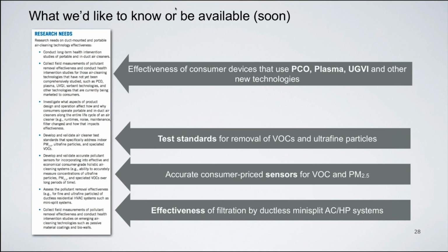And then there are ducted mini-splits as well, which do connect to very short, very small duct systems, same idea. But in both cases, those don't have filters that are very effective from the perspective of small particles. There may be one or two exceptions that aren't completely obvious in the marketplace, but the research that was done for the guidance strongly suggests that they really just don't have anything like a MERV 13 filter available in that class of equipment.